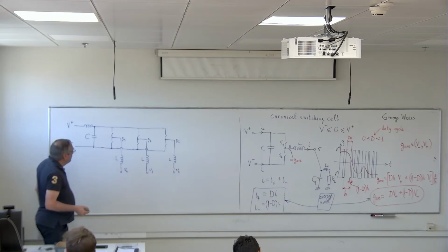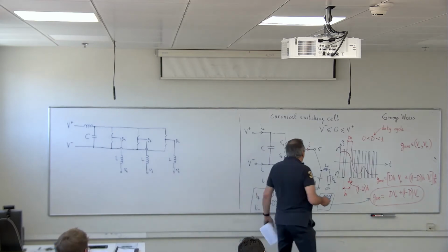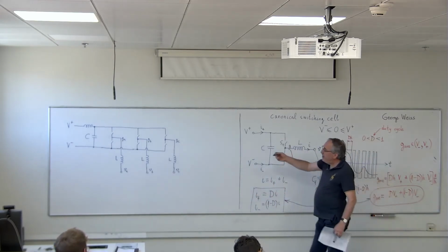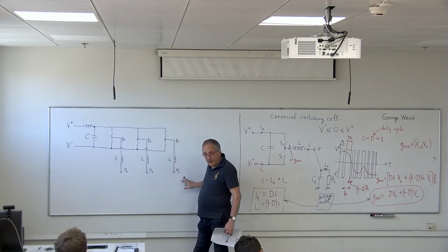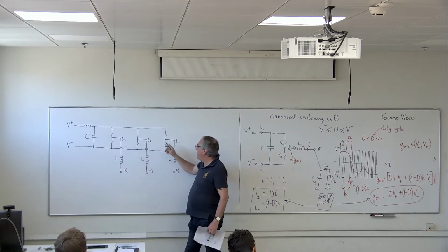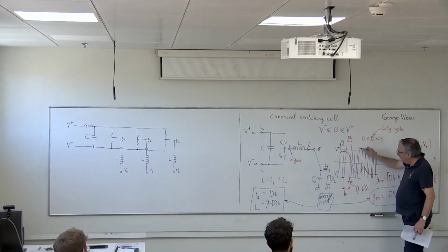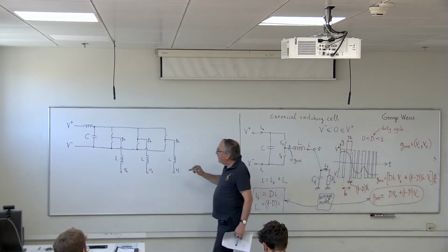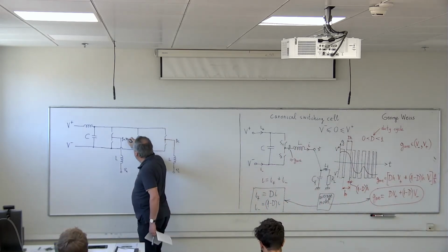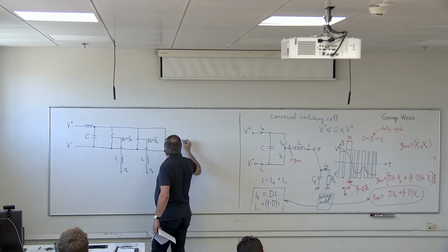If you generate GA, the signals GA and GB and GC, we usually denote the 3 phases by A, B, and C. So the signals GA, GB, and GC are, of course, ugly signals which have a lot of switchings in them, like I drew it here. But they can be approximated by their averages. Let's say GA tilde, GB tilde, and GC tilde,